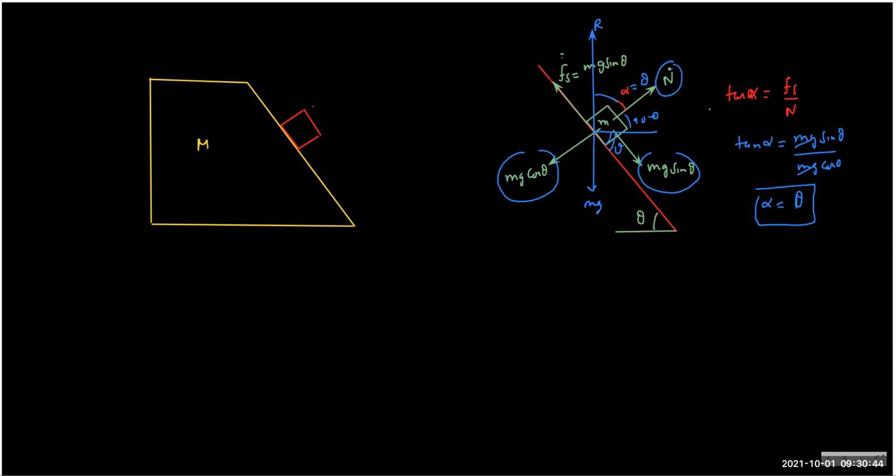So these two forces, which you normally draw, can be replaced by one force called the surface contact force. Of course, we do not have the habit of thinking about the R. We always think N and Fs, and we believe that these are two forces. But what I'm saying is we have only one force.